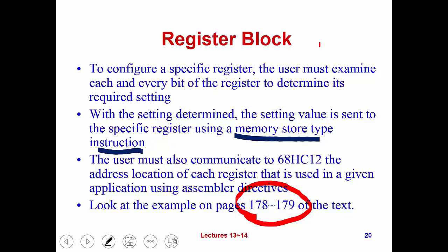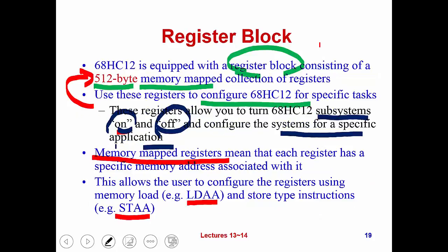Like you see right here, you see how we use EQU, how we use load, and how we use store. We can change the setting of a register, so it can change the configuration or turn on or turn off hardware subsystems. Here I show you. Same idea for other registers and the corresponding subsystems.